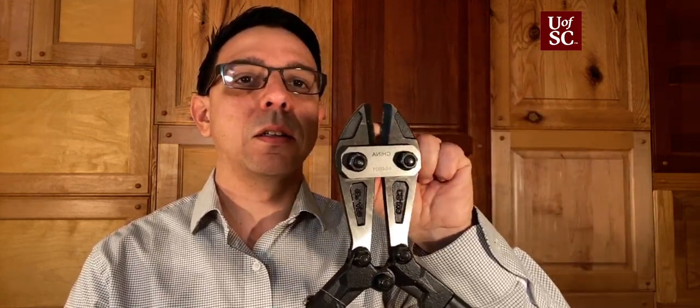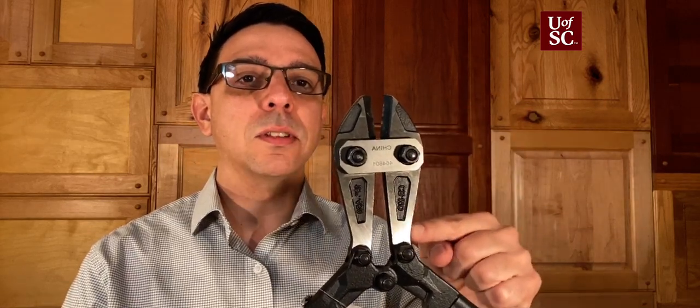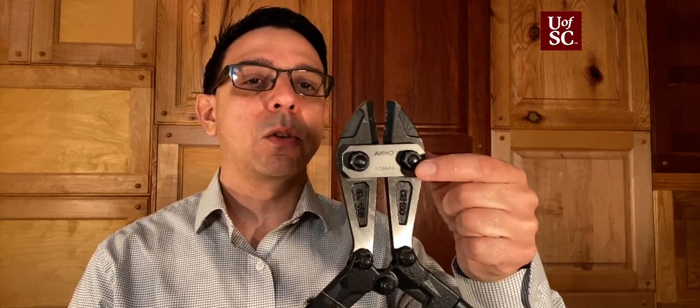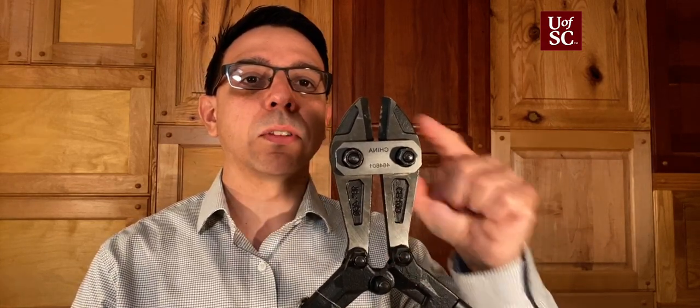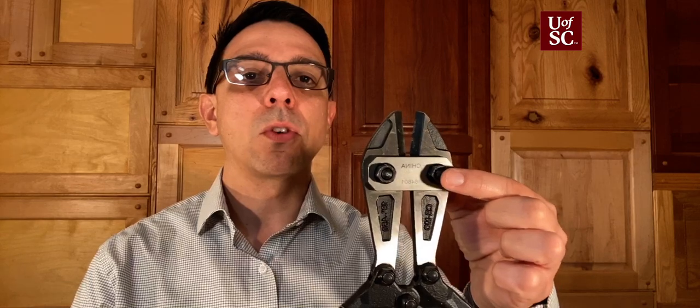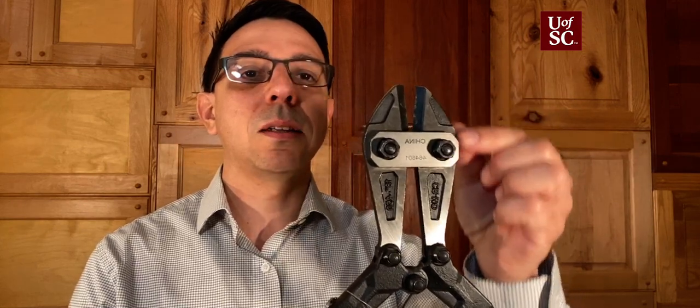If we put something here to cut, we're going to see that these long elements on the sides are going to have one force, the one coming from the thing that is cutting, another one from this pin, another one from this pin. So in that case, these long elements are going to be multi-force members. In the case of this element over here, it's only going to be a two-force member because it is only having the forces by the two pins, this pin and this pin. So this particular system is a machine because it moves, and it can be analyzed using statics by breaking down the different elements and analyzing the different elements.